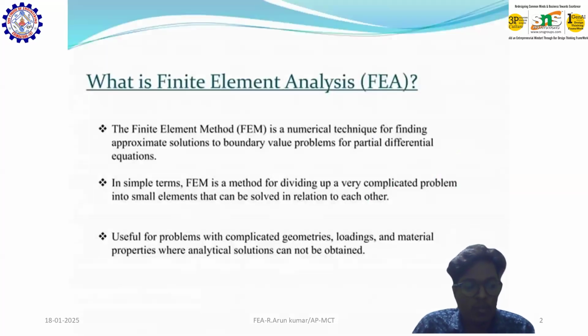So first of all, what is the meaning of finite element analysis? Finite element analysis is one of the numerical or approximation methods for solving differential equations. That is the foremost thing. Finite element analysis, simply called FEA or FEM, is a numerical technique to find approximate solutions to boundary value problems for partial differential equations. In simple terms, FEA is a method for dividing up a complicated problem into small elements.